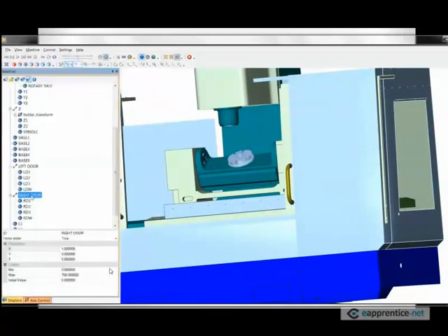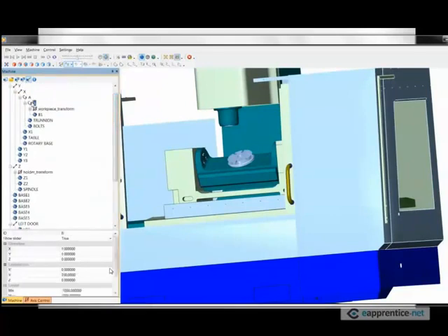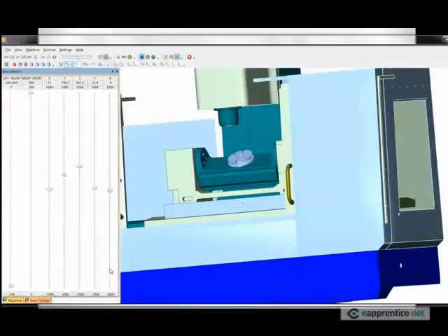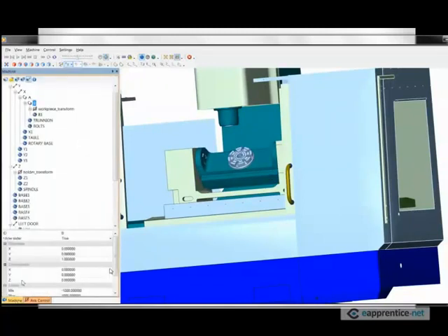Let's go back to the machine, go to my B axis. There we go, B axis, and change that from the Y direction to the Z direction just by typing in 1 around Z. That's just a vector direction. And now if I go back to axis control and rotate B, it's rotating the way it should. Now my A is rotating way too much, so I probably need to put some limits, and usually on a machine like this the limit is plus minus 120.